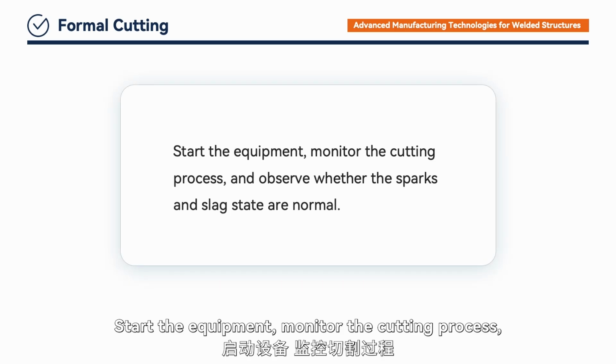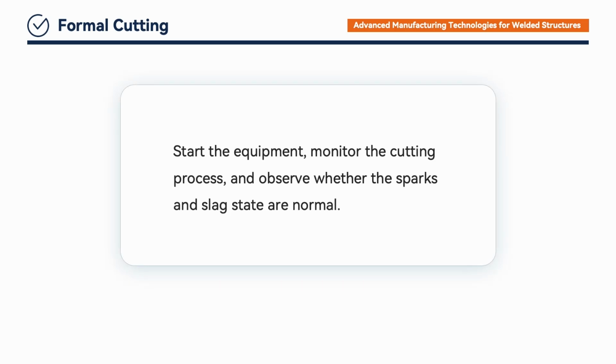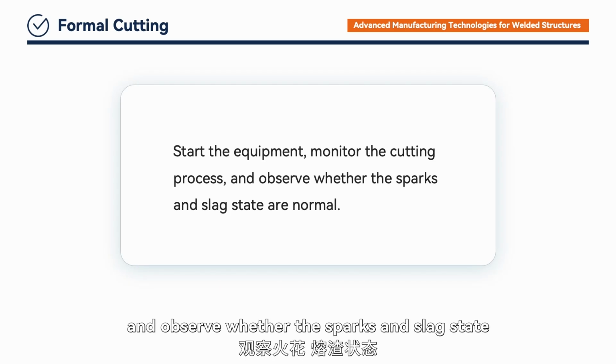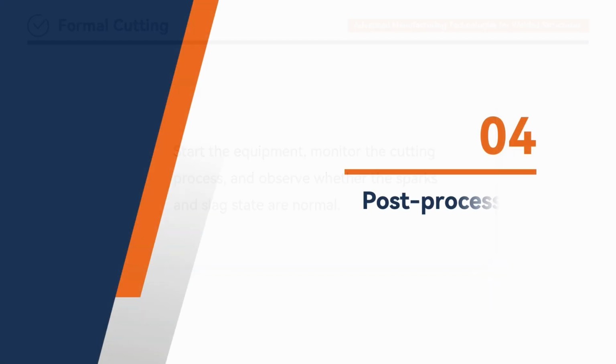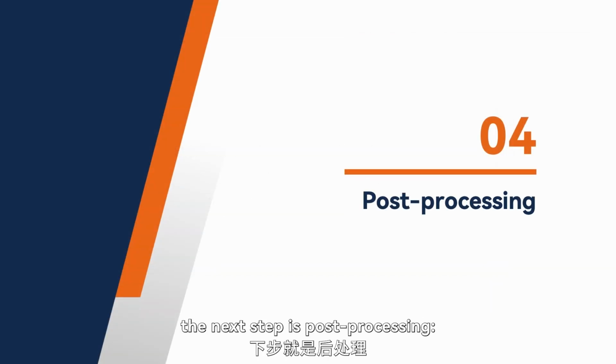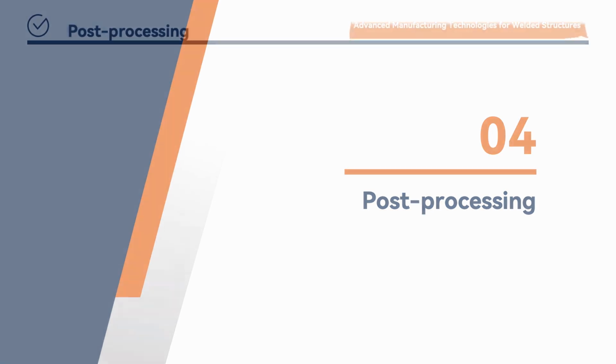Start the equipment, monitor the cutting process, and observe whether the sparks and slag state are normal. After the cutting is completed, the next step is post-processing.